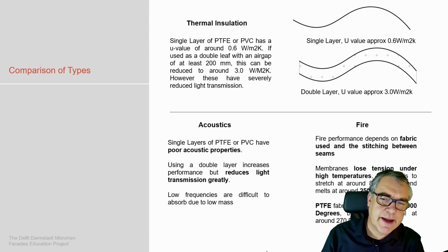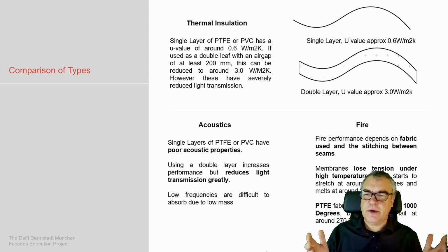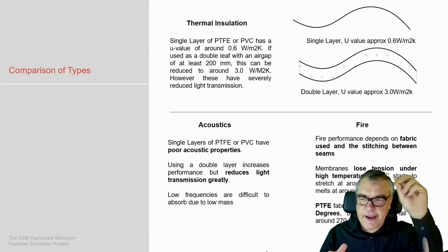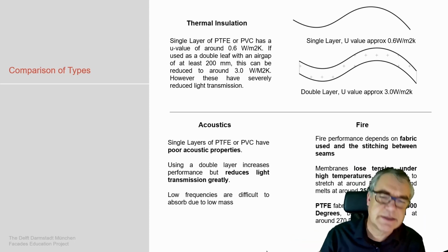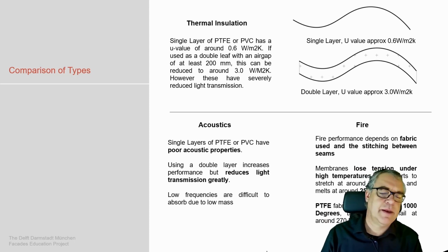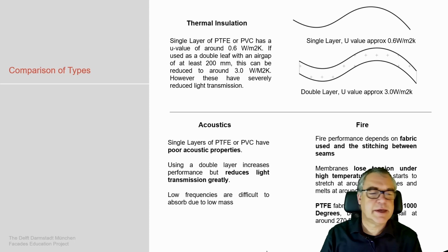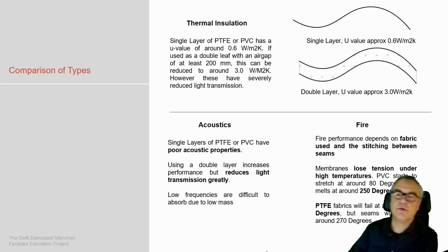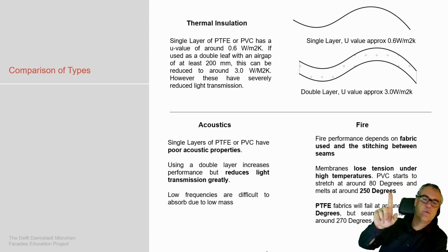Acoustics, now yeah, it's actually like a drum. You have a pre-stressed structure. If rain hits this, you obviously get a noise. So acoustically, these tensile structures are always a complex one. You may think about adding weight, but then the light structure disappears. So that's a downside. And then there comes the fire, which I need to show here as well.